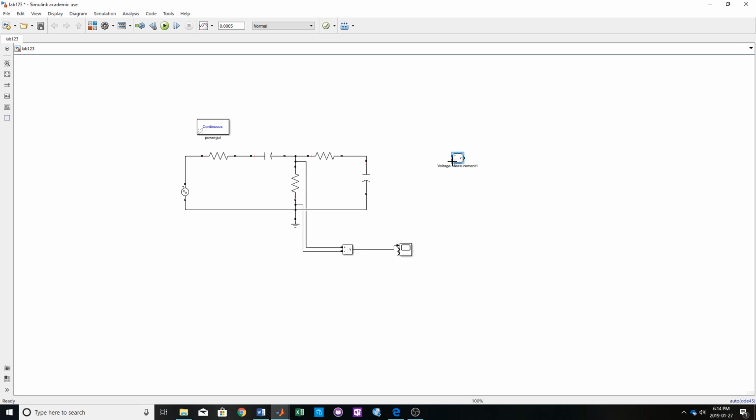All right, so let's just copy this element. So this is the easiest way to do it, and then you're gonna paste it here. And let's say you want to track also at the same time, in the same scope, the voltage across this capacitor. So what we're gonna do is, like, we're just gonna connect it across, like so. Let me just, if I can connect it. Oh, what the heck. So you're gonna take these leads here and connect them like that. Like that. Okay. Okay, so that's gonna track the voltage across the capacitor. Okay, it's pretty self-explanatory. You're gonna go over here, and then you're gonna connect it to the second port of the oscilloscope, let's say. Okay, all right.